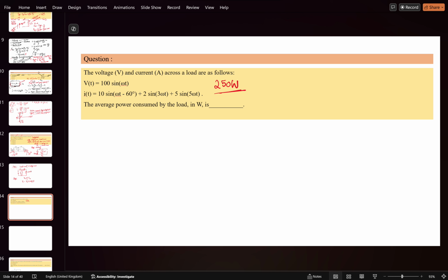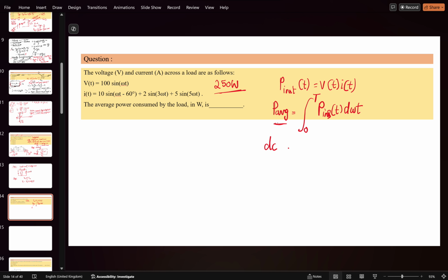Okay. So there is one thing: when you multiply the DC term of any voltage or current with any frequency term, it will become zero in the average form. You can see the derivation of the average power in some book, and this concept will come into the picture: when you multiply a DC term with a frequency term, a sinusoidal or cos term, it will become zero.